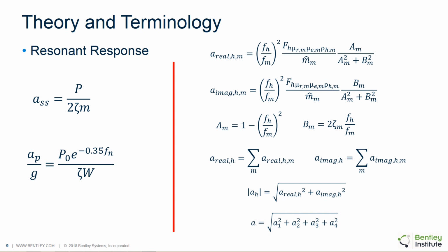So in other words, you'll see the weight term in there, which cancels out the 2 term in the denominator, and then we have the gravity term, which is also introduced because we're converting from mass to weight. But essentially we're applying this for the simply supported beam, where we knew that the modal mass was 1/2 of the total mass. And so that's the assumption that's made here in this equation.